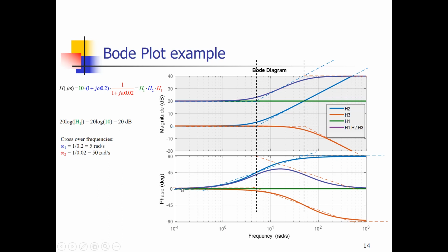So we start off at 0. But for very high values of omega going to an infinite value, we get the arctangent of an infinite value, which is 90 degrees. So we end up at 90 degrees. And then we can construct the Bode phase plot for the system using the cutoff frequency, a frequency 5 times less and 5 times higher, and then we get the blue dashed line. Again, this line is the real line and the dashed line is the asymptotic line in which we are interested.